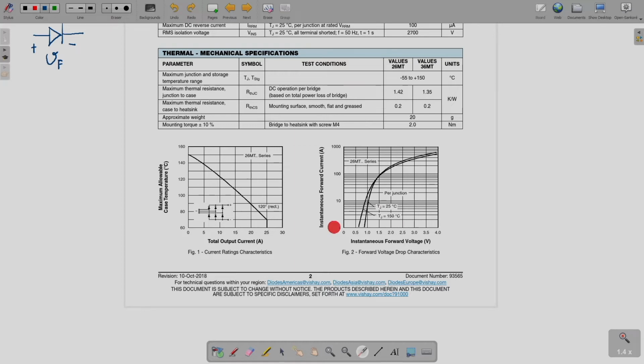Then here this is forward current versus forward voltage of the rectifier bridge that is provided over here. So, what you see is that two curves are given over here, and this 0.5 to 1 volt is what you can expect to be the initial threshold voltage, because they have started from here, but you can recheck it with whatever is given above.